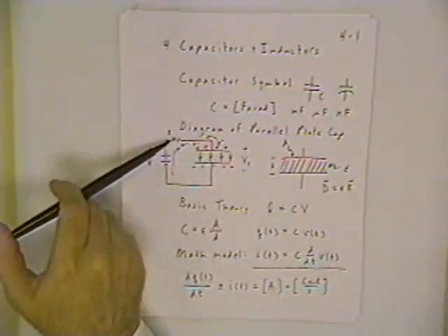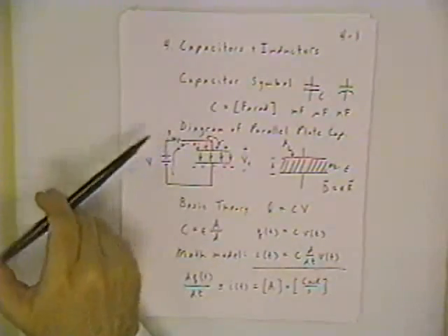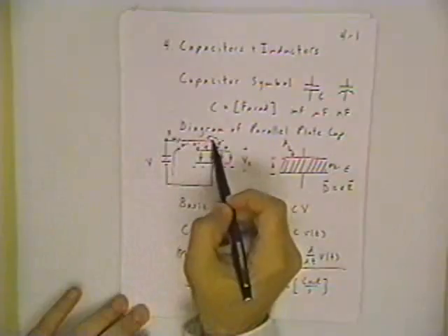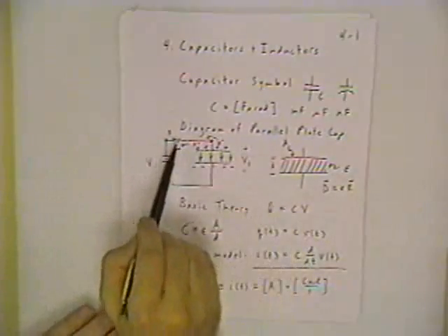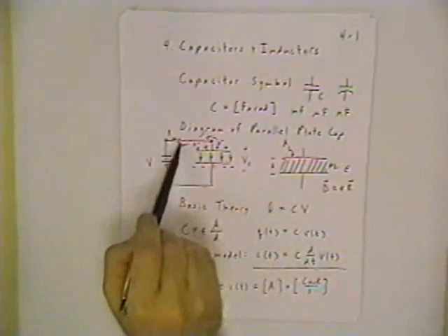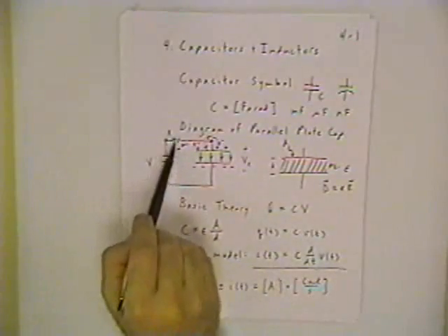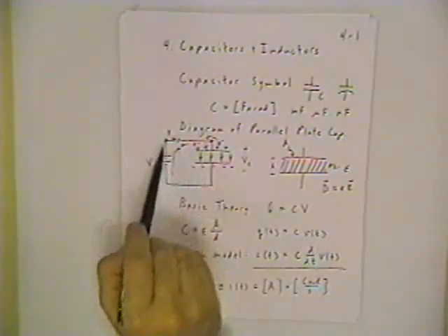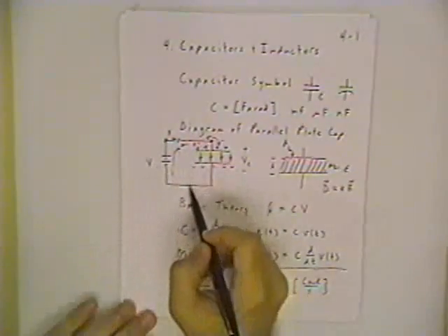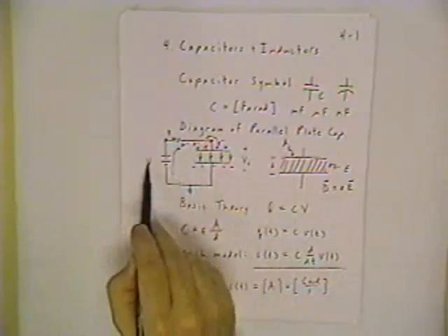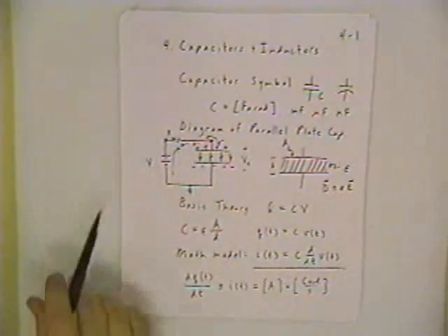The only way this resistor has any current flowing through it is if there's a potential difference across it. So comparing this node and this node in the circuit, if that potential difference is 0, there'll be no more current. And if that current is 0, then the voltage at this node is equal to the voltage at that node. They're both equal to V. And that shows that with respect to the ground node here, the capacitor has fully charged to V volts.